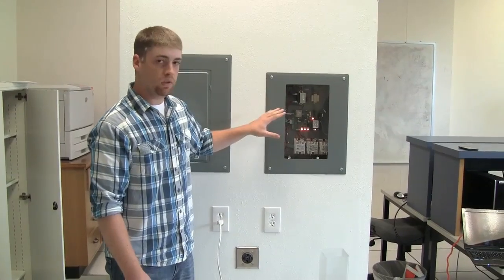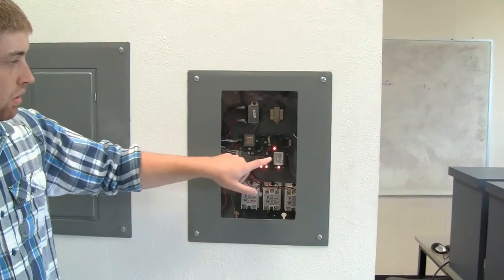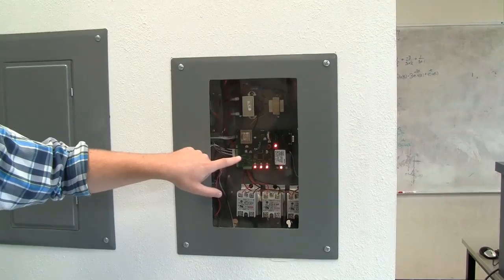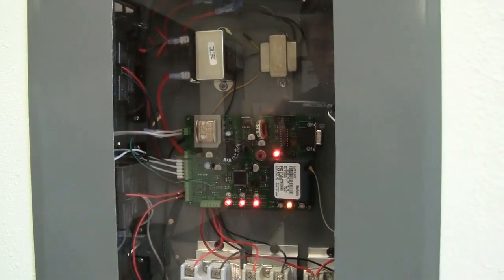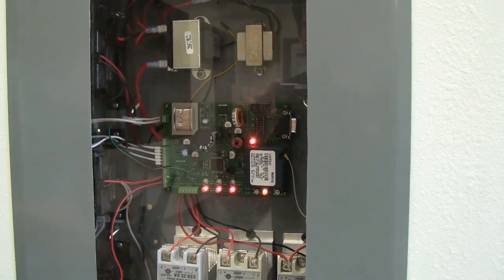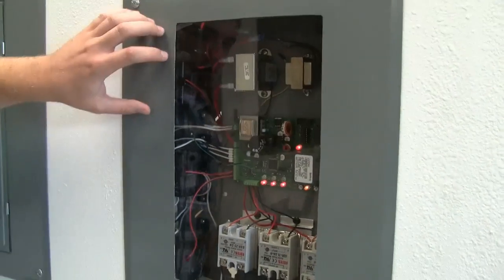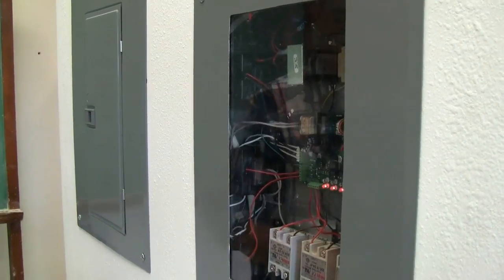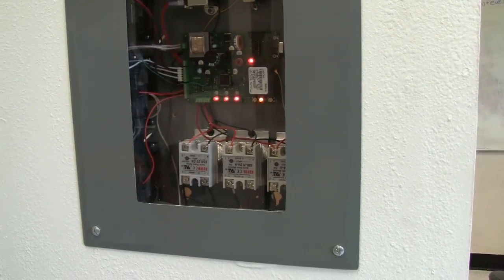A little tour of what's going on over here itself. The circuit board here contains the wireless device, the Lantronix MatchPort. It has an ATmega128 microcontroller. There are some LEDs, sets of red and green, that indicate the status of the appliance, whether it's on or off. Red is off, green is on. Behind here, there are some Veris current transformers, and those give us the current measurement, the magnitude of the current. And right here, some solid state relays. This is what actually cuts the power on and off to our devices.